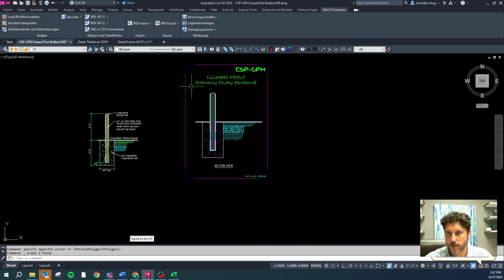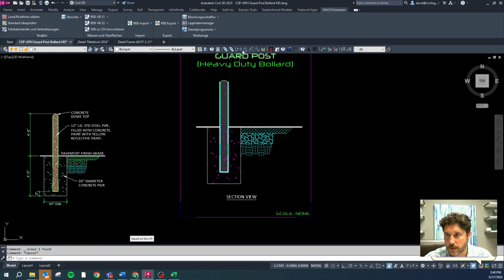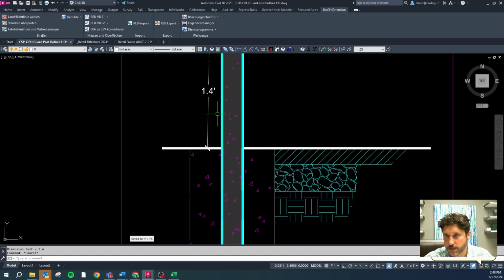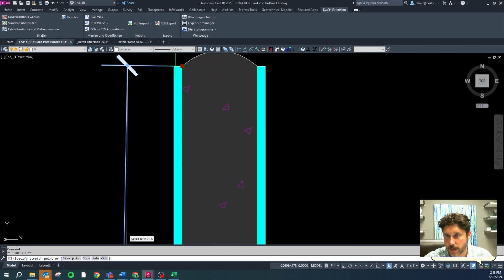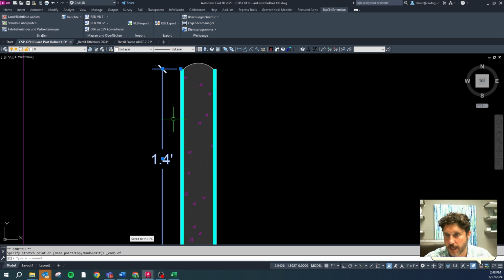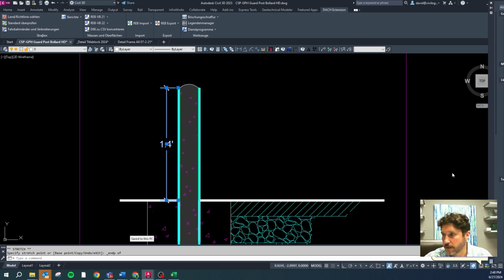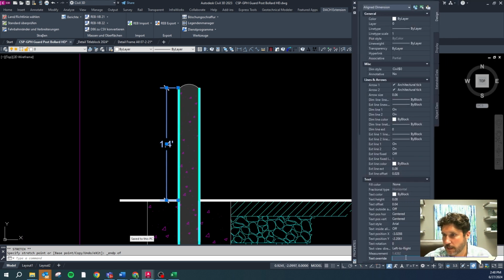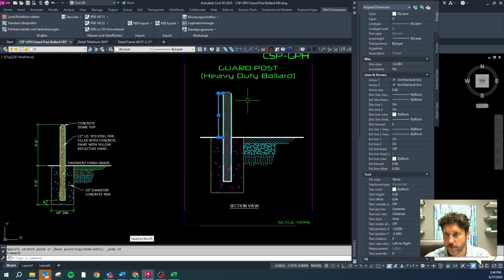So both of those will work. So let's do some dimensioning. Now, keep in mind that this thing is actually a lot smaller, so when I dimension that, it's going to come up with a smaller size, and that's because I shrunk the block down. But we can just go over here to our overrides text, and I want that to be 4 feet. So I'm going to type in 4 feet.